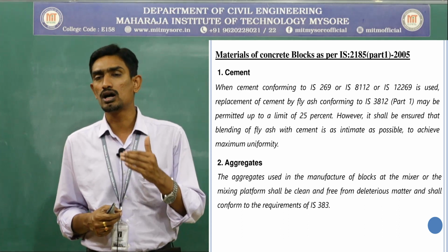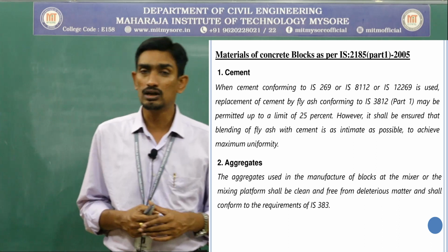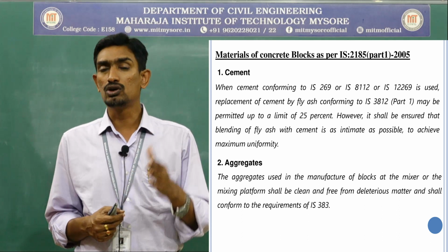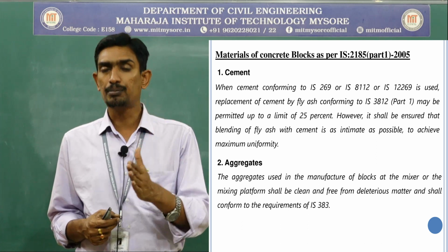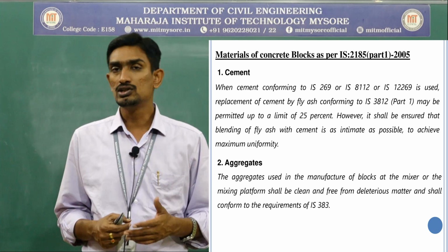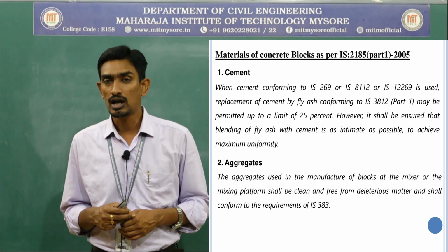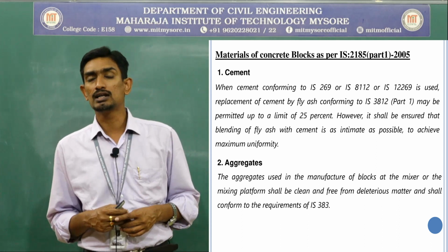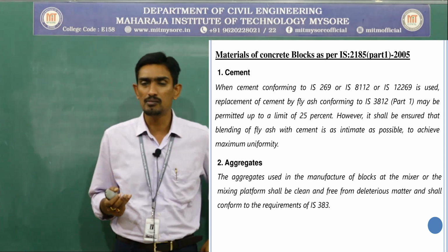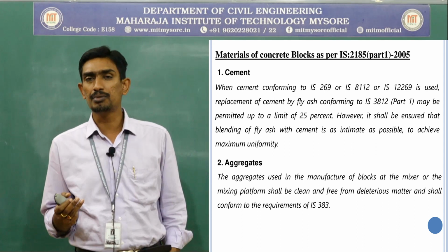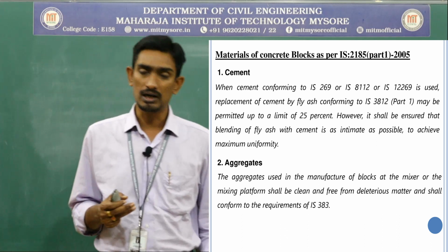That means after burning the coke or iron in the blast furnace, the residue left out is the granulated blast furnace slag. When I grind it finer, to the fineness of cement, that particular material can also be used as a replacement. Jindal is coming up with this replacement of cement with ground granulated blast furnace slag as Portland Slag Cement. So these are the types of cement available in the market; by using PPC and PSC, we can achieve the green concept in cement.